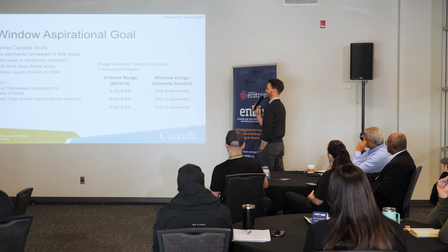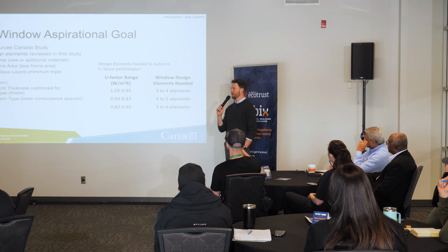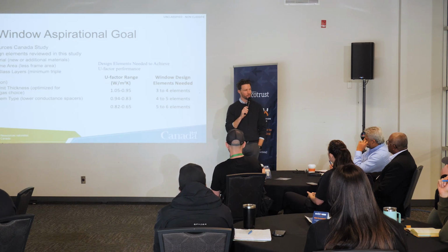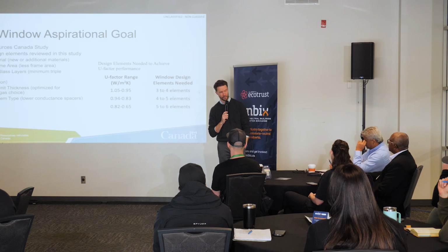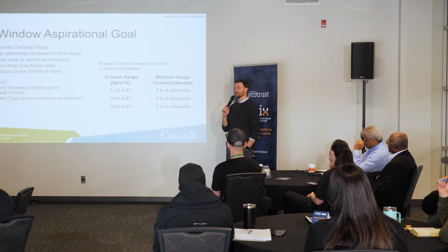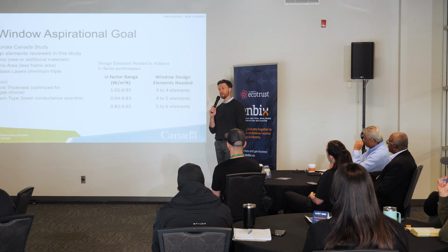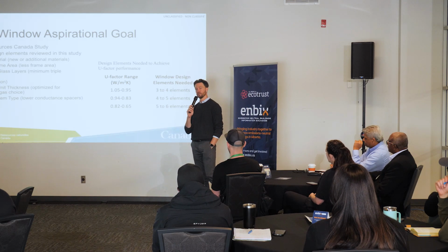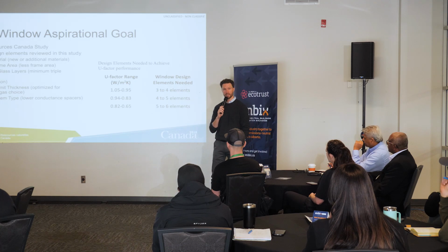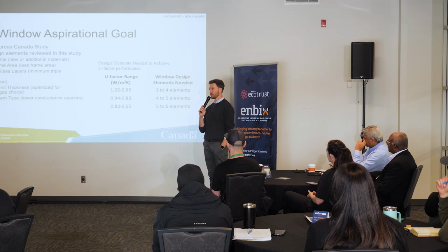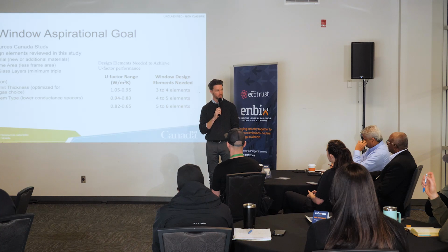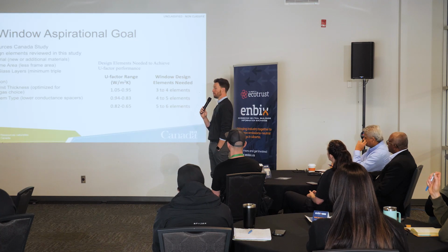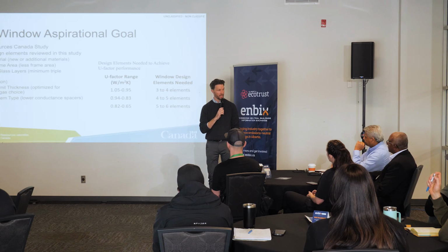It was, and I'm going to be careful how I say this, an imported European style tilt and turn. And the reason I'm cautious saying that is that windows coming from overseas are tested using different test standards, and you cannot directly compare a European test standard U value to a North American test standard U value because they test them at different temperatures and different sizes. But we did get values for both in this case, and so the 0.78 I gave was by the North American standard for that window, but it was a tilt and turn window.